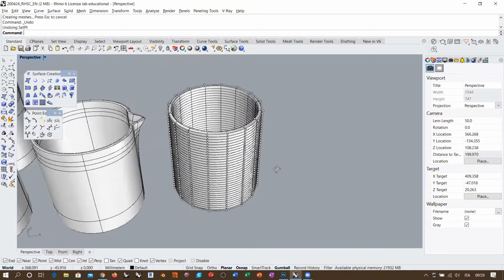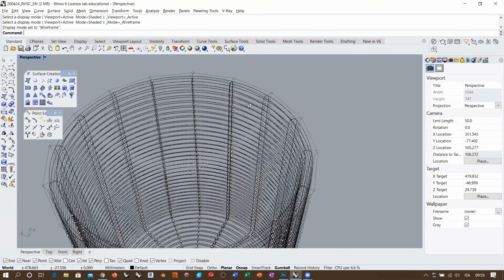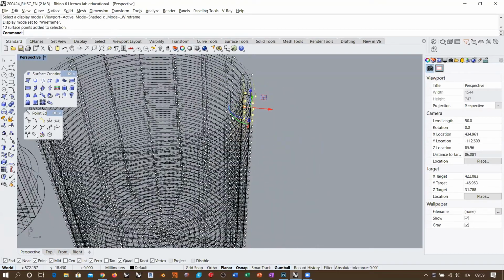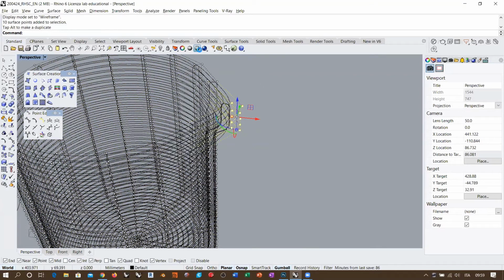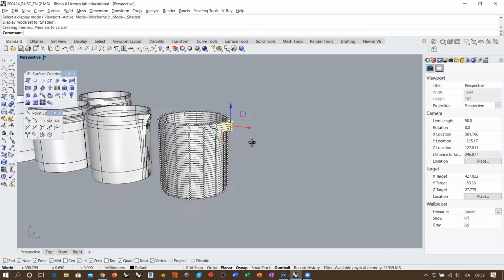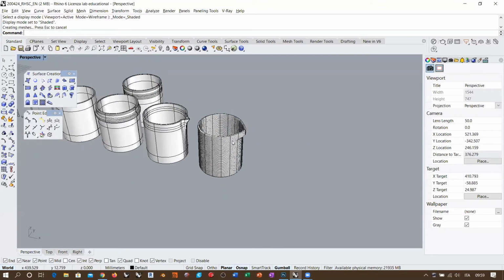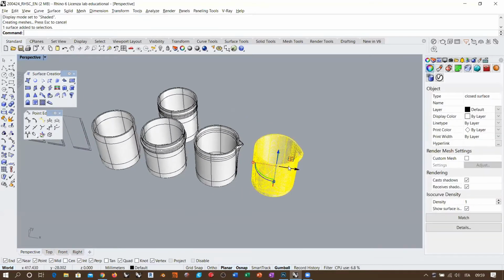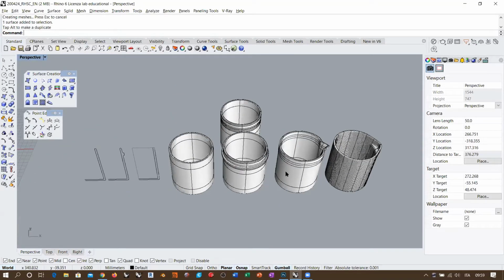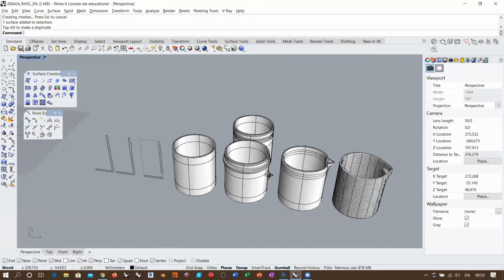Of course, if you do this, on the other hand, there is some advantage, because you already have a degree 3 surface that you can edit however you want to create the local deformation, but at what price? Okay, so this is basically the main difference in working with a direct topological approach or with some kind of generic topological approach like the rebuild commands. Okay.